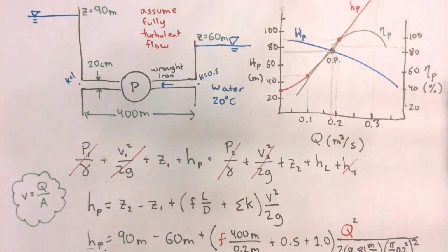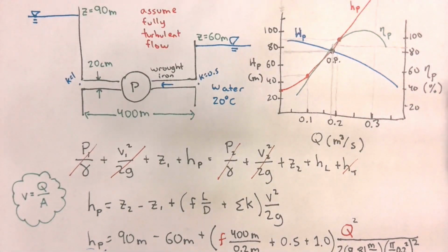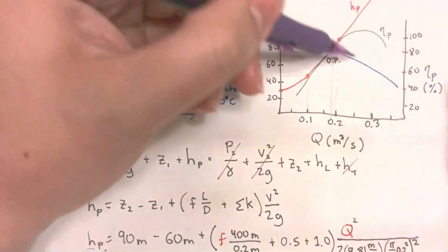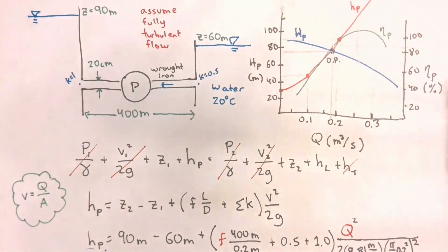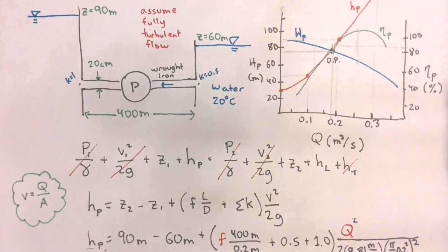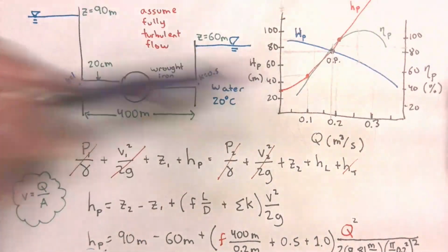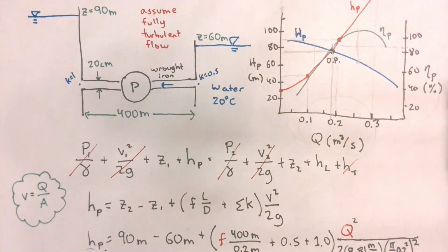So I think he's trying to figure out exactly what their relationship is there. And my answer to him was that it was because OP was under the efficiency line. So you had to go up above OP to hit the efficiency. Exactly. If my OP would have been here, then my efficiency line would have been up here, right? If OP had been to the left of it, wouldn't you have to go down? Exactly. If my OP would have been here, my efficiency line would have been here. Because the efficiency line relates flow rate only to efficiency. Has nothing to do with the pump head itself, right? Yeah, thank you for sharing that.